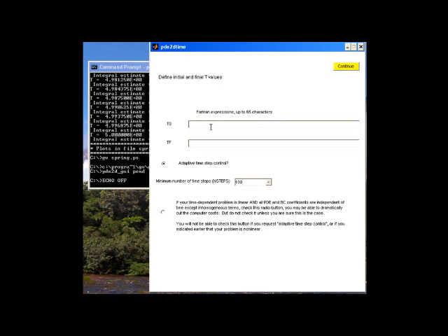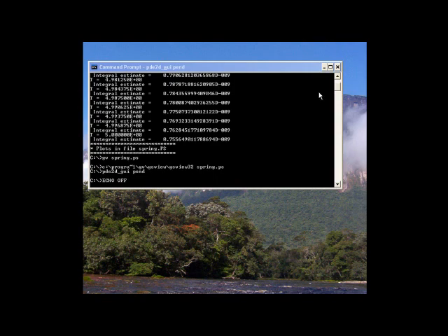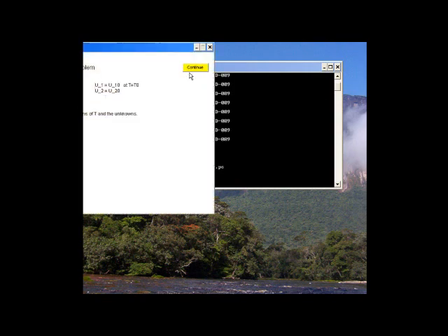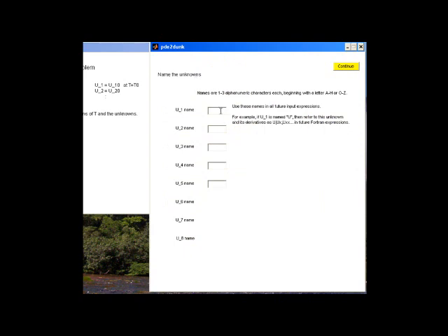Let's go from 0 to 5. And I don't want adaptive time step control. We'll discuss that later. You wouldn't know this, but I don't want it. There's a reason for it. You can always change it later. The discussion in the book explains why you don't want an adaptive time step. Normally you do, but for this particular problem, this differential algebraic system, you don't.